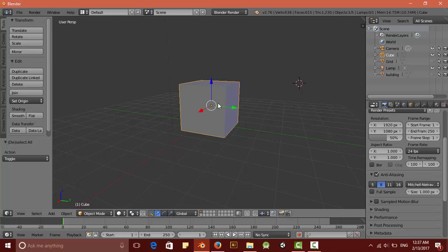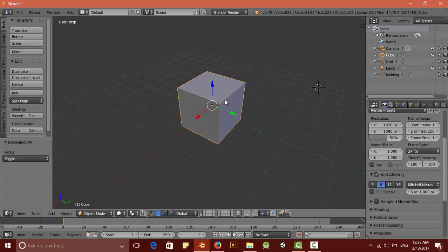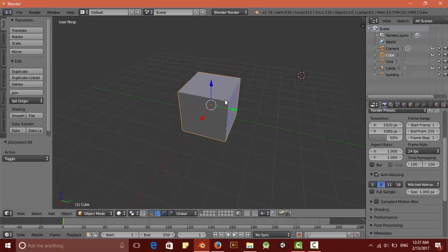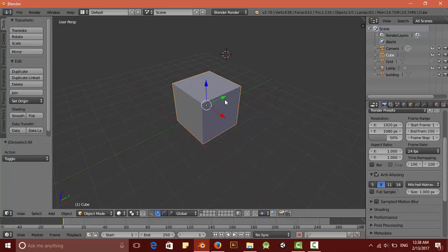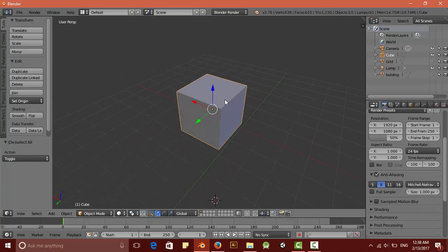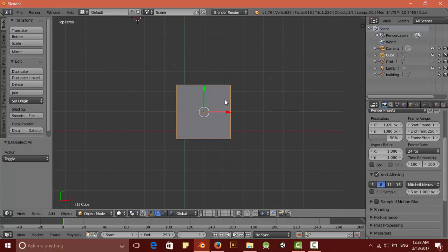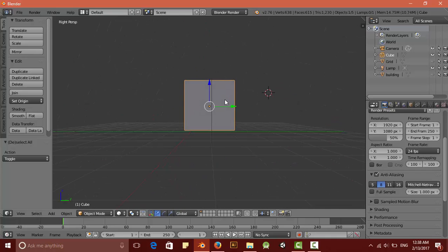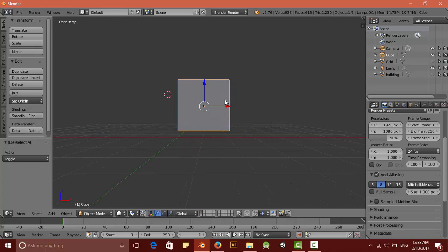There are also some shortcuts and hotkeys for this interface. If you are using a keyboard with a numpad, you can directly change the view. Num 4 for rotating to one side, 6 for moving to the other side, 7 for top view, 3 for right view, 1 for left view.